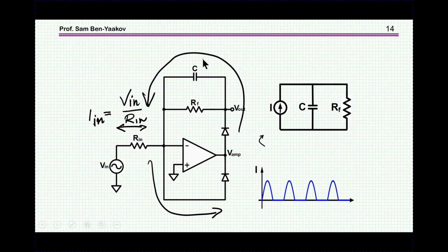The current flowing through here is actually determined by Rin, because here we have a virtual ground, so therefore the current here will be sinusoidal, or halfway sinusoidal. The magnitude will be V in over Rin. This is the current here, no matter what you have here, because this amplifier maintains zero between these two terminals. And therefore, here we have virtual ground, and the current is the voltage across this resistor divided by resistance. So this is the current which is pumped in.